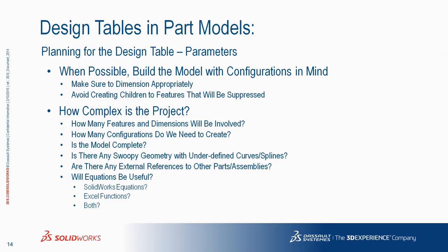We also want to look at whether there are any external references to other parts or assemblies. Will equations ultimately be useful? If so, what kind of equations are you going to be using? SOLIDWORKS equations? Are you going to be using Excel functions? Or are you going to be using both? More often than not, I find you end up using both. And you've got to be careful of that because they can cause conflicts with each other.